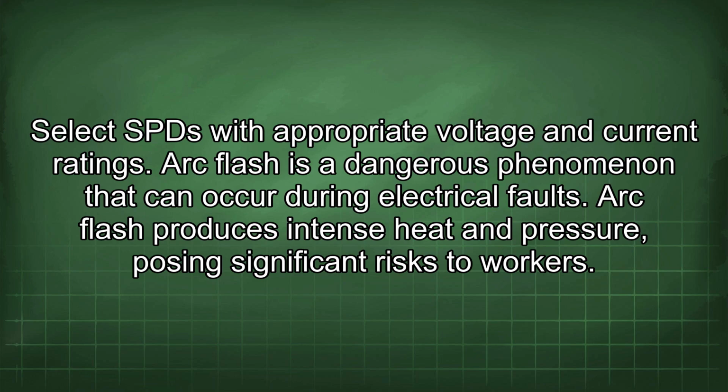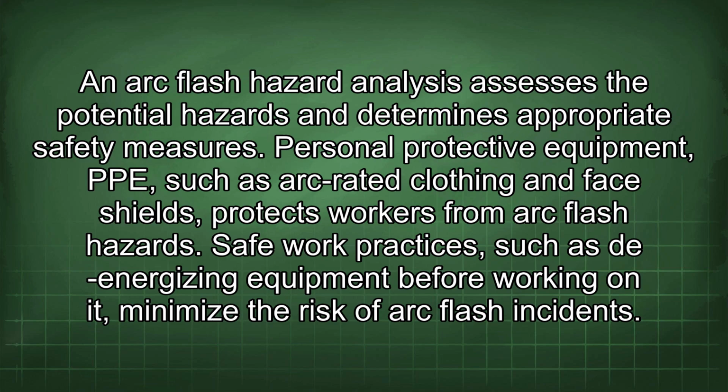Arc flash is a dangerous phenomenon that can occur during electrical faults. Arc flash produces intense heat and pressure, posing significant risks to workers. An arc flash hazard analysis assesses the potential hazards and determines appropriate safety measures. Personal protective equipment, PPE, such as arc-rated clothing and face shields, protects workers from arc flash hazards. Safe work practices, such as de-energizing equipment before working on it, minimize the risk of an arc flash incident.